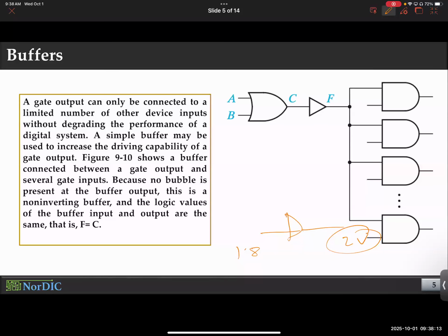Any logic gate will take your voltage to full 0 and VDD. This is called rail to rail swing. Okay, this is known in VLSI design. Rail, basically, means VDD and ground. So it takes you all the way to the ceiling or floor, depending on what you want. Okay, it's not like only the VDD that gets contaminated. Sometimes ground changes too.